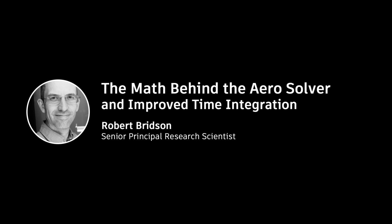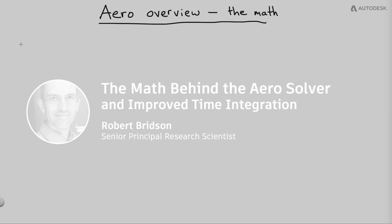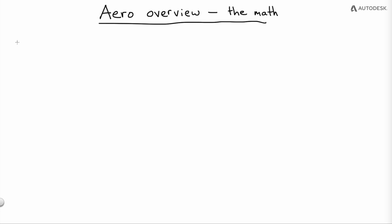I'll be giving an overview of the Aero solver, the math and the algorithms behind it, as well as talking about our new improved time integration, both what it is under the hood and what kind of improvement you get out of it. The first thing I should emphasize is that Bifrost Aero is an Eulerian solver.